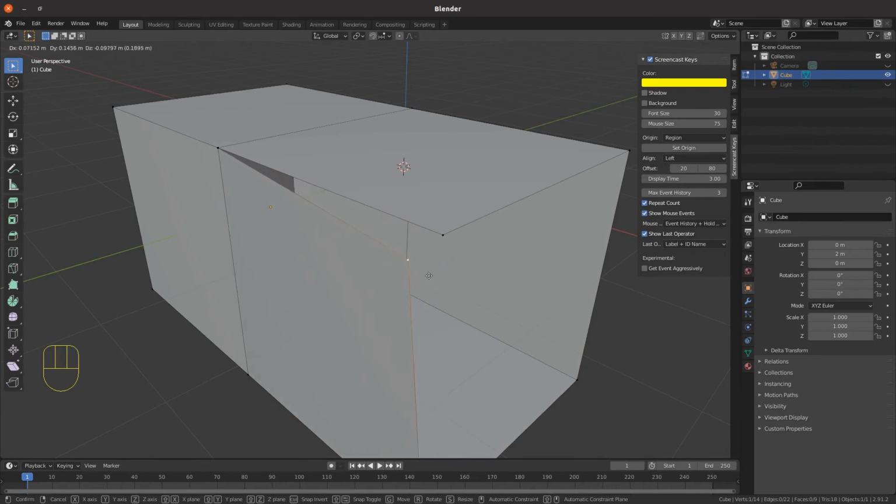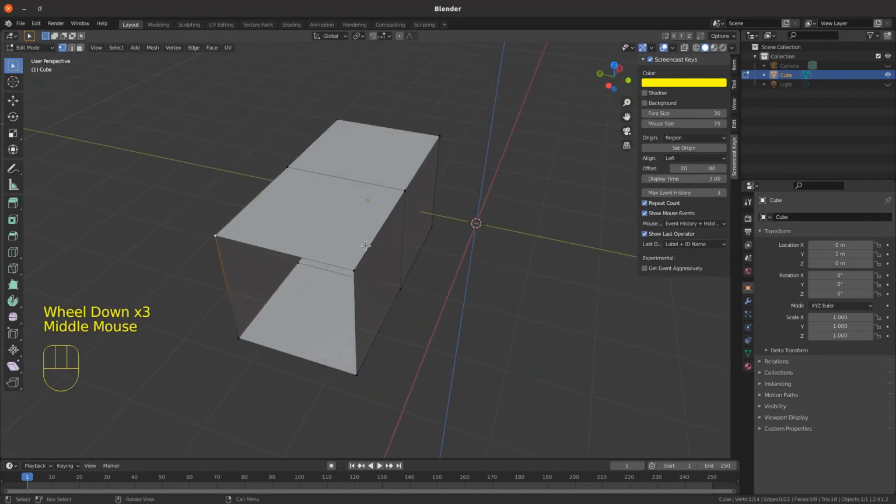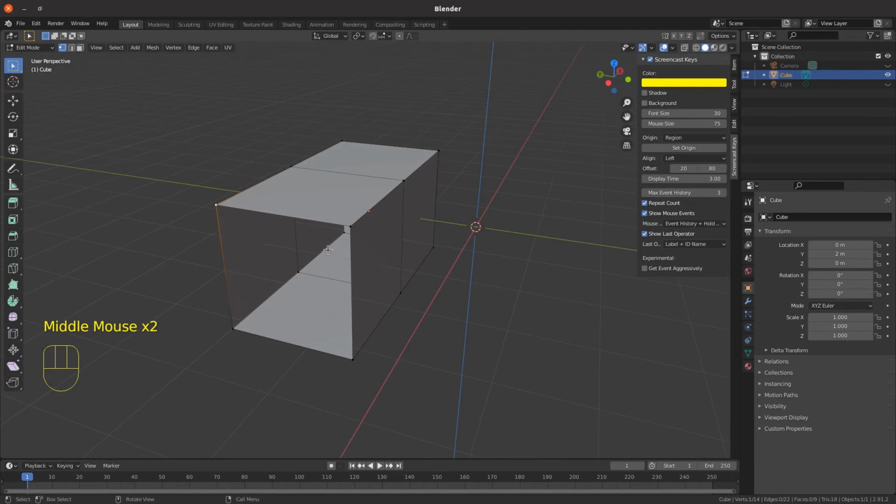Before you enter to accept the move, you can press escape and it will return it back to where it was. And there's a merge feature that allows you to remove doubled vertices. So it's exactly the same on that corner, made up of 2 vertices, because when we extrude it out, it doesn't automatically weld them to vertices that they're sitting on top of.